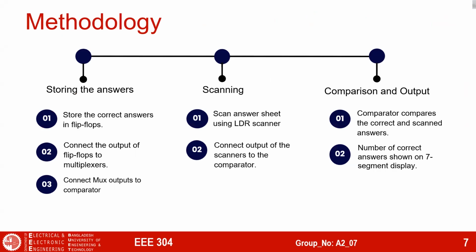Our project can be divided into three parts. First, we have to store the correct answer. For that reason, we have used a number of flip-flops. Then we connect the output of the flip-flops to the multiplexer, and then the multiplexer outputs to a comparator.